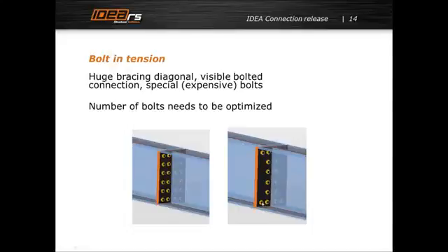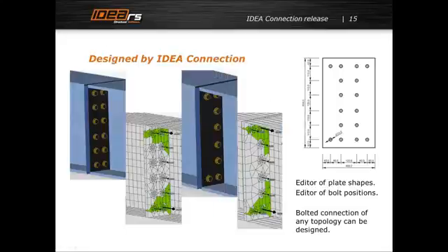And again, we were not able with current tools to calculate such a group of bolts. Now we can, and we have an editor of bolts, so you can start with this regular group, and then delete the bolts which you do not want to have. And because we calculate with finite elements, we can do, in fact, a general layout of bolts.